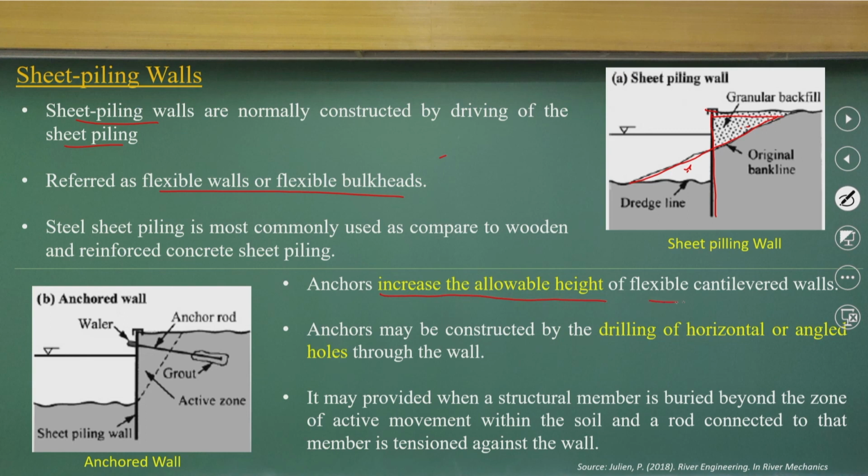With a flexible cantilever, you can have anchors and sheet piling. You can do the geotechnical design of the sheet piling: what the depth could be, what type of anchoring you should provide, and what the strength of the anchoring is. You can look at those things from a geotechnical perspective, and whether it has a cut and fill or an anchored wall.